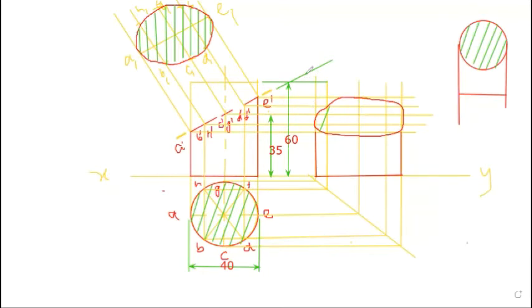So all of you first extend this line and you show the angle like this. So this will be the 45 degree. So draw the extended chain thin line thick at two edges here and here. This will be the 45 degree. So in this way you can show the angle of the cutting plane.